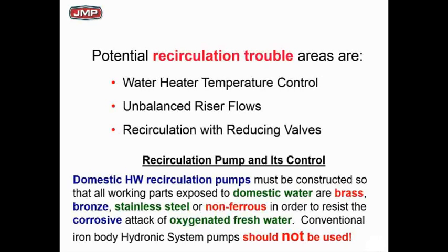Under water heater temperature control, where you have instantaneous water heaters, you need to up the recirc rate to maintain control. So the first place to look is instantaneous water heater control, where you have small recirc pumps. You're going to have temperature control problems at low flow and low draws. The way to handle that is to upsize your recirc pump. So in that case, we want to size it on some minimum flow, not on the heat loss.